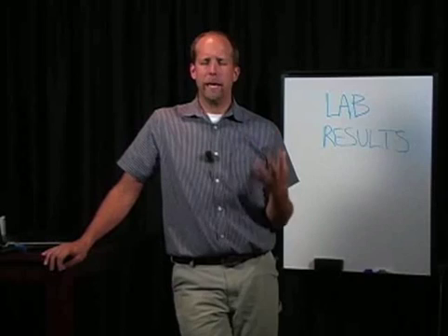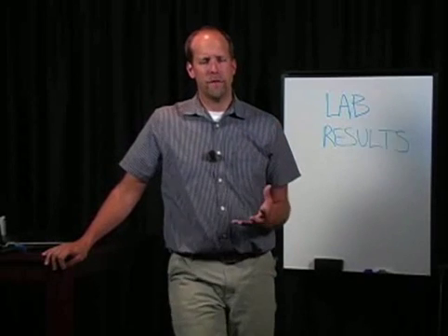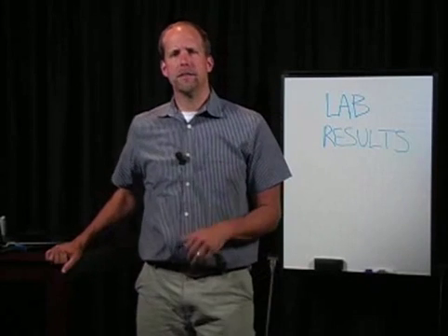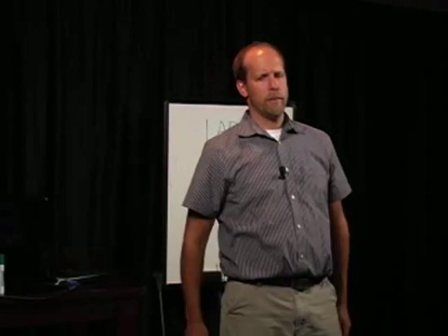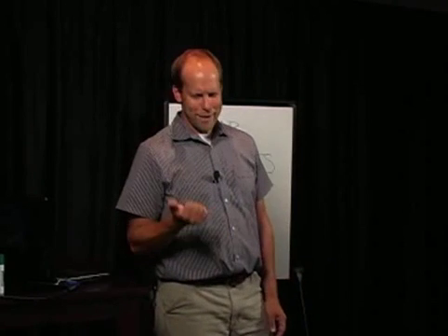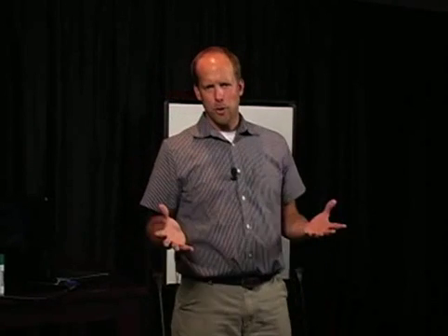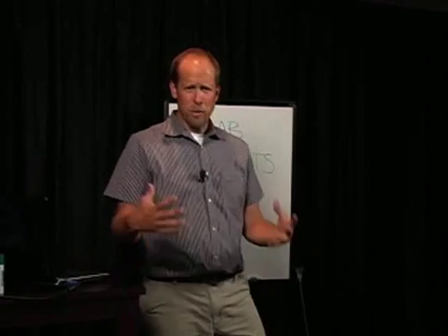Carpeting that's wet: dry the carpeting immediately, at least within 48 hours. Don't let it go over 2 days. Remove the water with a wet vac. Pull the carpet and pad up off the floor and dry them using a fan to blow air over them. The wet vac can be rented at your local home center, and also the blower fans too.